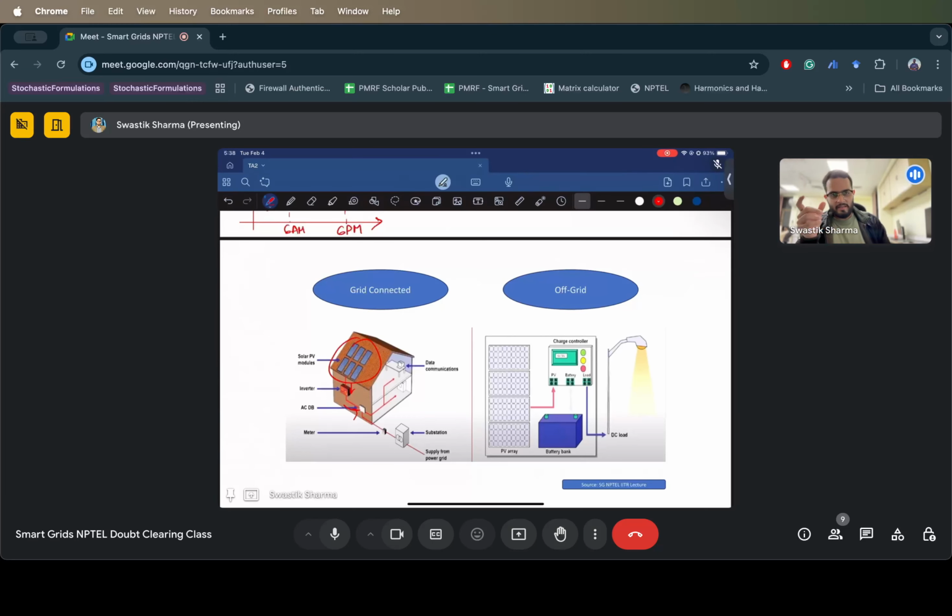So when electricity supply comes to your home, it is not straight away used to power your loads, right? It goes to a distribution box where there are multiple MCBs, and only after that is it used to supply your loads in your household, right? Why is that? Because you want to protect against a sudden fault, so that it does not creep in and disturb or impact your loads. So that's why you use an ACDB, which is then connected to your meter.